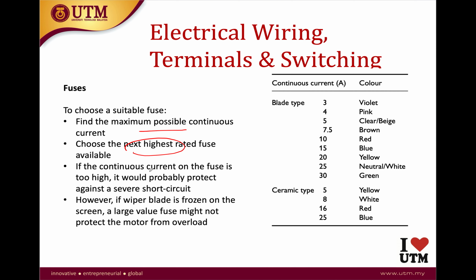If the continuous current rating of the fuse is too high, it will probably still protect against a severe short circuit. However, let's say your wiper blade is frozen, a large value fuse might not protect the motor from overload. This is assuming that you are staying in a four-season country where you have winter, where it's going to be very cold and the wiper blade motor is frozen.